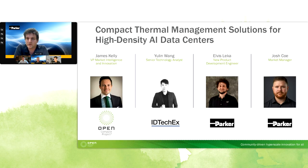And the refrigerants being used in pump two-phase refrigerants for direct-to-chip cooling all have a GWP of under 750. Most of them have a GWP very close to 1, the low-pressure refrigerants, and even the medium pressure refrigerants have a GWP that's close to 200 or 300. But on the refrigerant side, refrigerants are an engineered fluid. So there's a lot of companies out there that are doing a lot of work to come up with the best and most appropriate refrigerants to use so that you don't have to worry about the GWP and you don't have to worry about the PFAS as much as well. So I hope that answers the question.